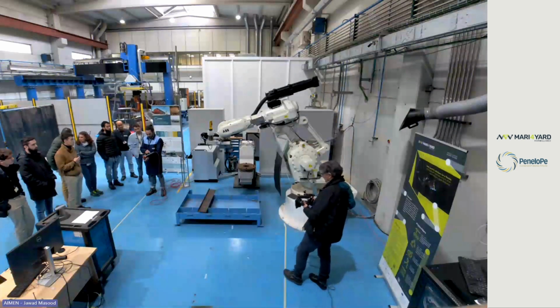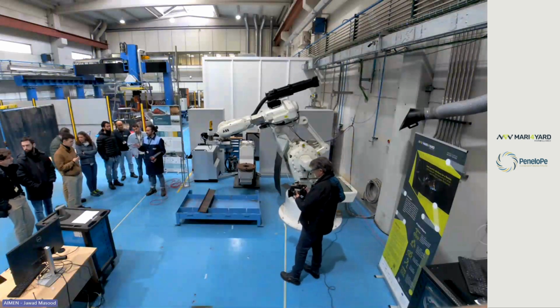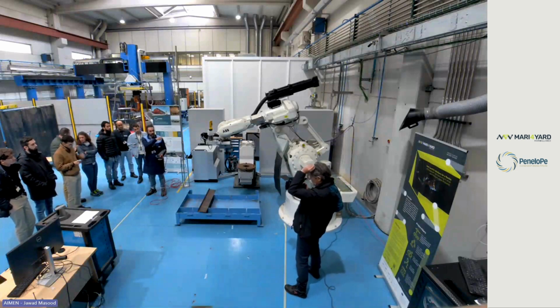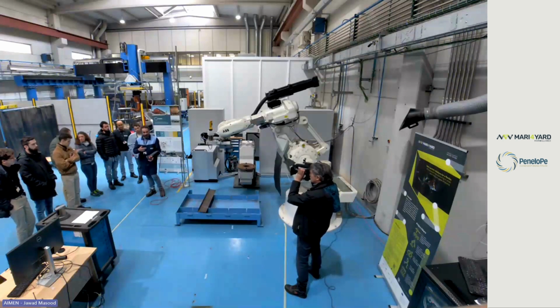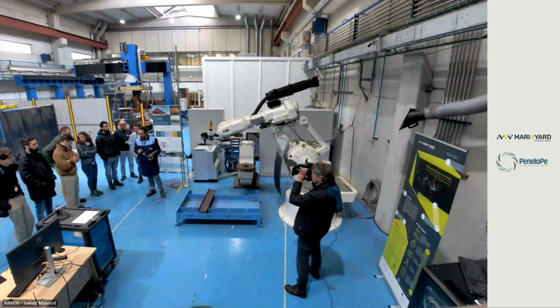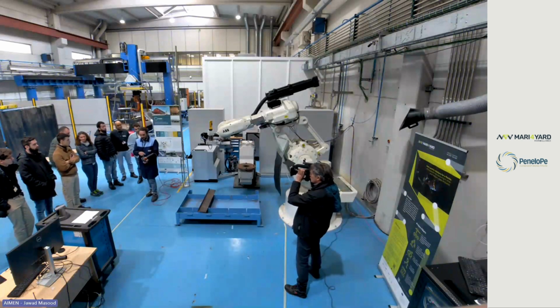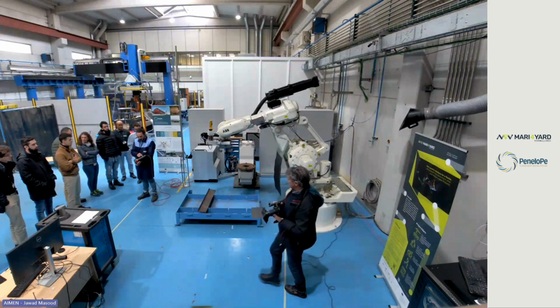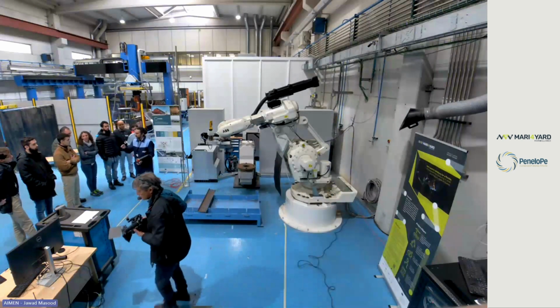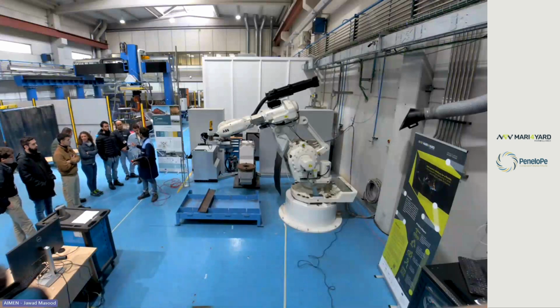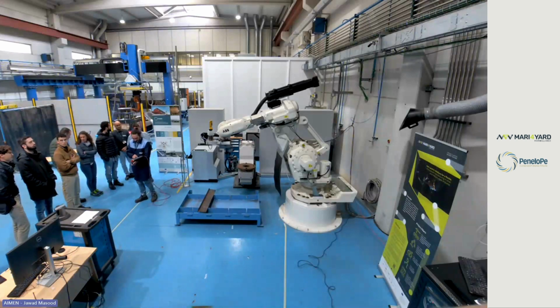Okay, modify position, modify. Now this position with the coordinates is saved in the robot's program memory. So we can proceed with the next movement instructions. Now, if we want to perform a square, for example, we have to go to the square routine to start introducing the different move L instructions to perform this square.